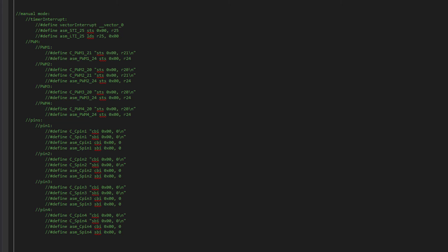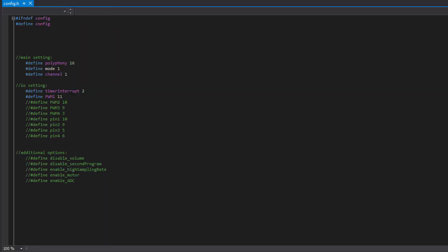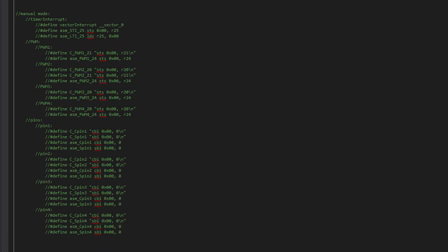The use is simple, you need to define the addresses of new pins or timers and that's it. To find out which address should be entered, check the processor's documentation which address corresponds to a given pin. All definitions related to a specific pin, PWM, or counter should be defined. Do not define the same thing in manual and normal mode. The pins must be set to the output in the sketch yourself, and the counters used should be manually set to non-inverting 8-bit fast PWM and, if necessary, they should also be synchronized. And that's it when it comes to pin configuration.